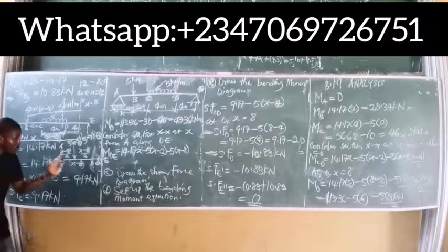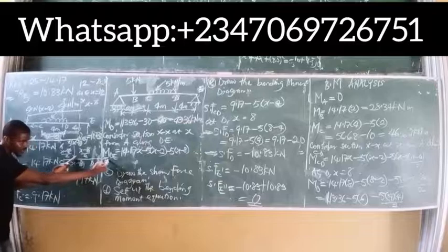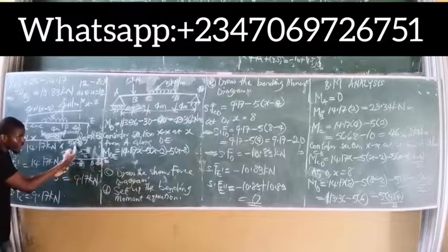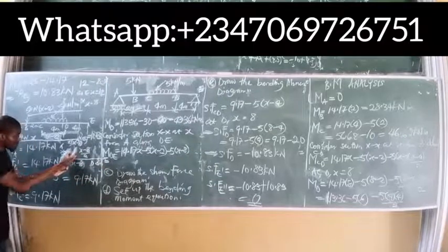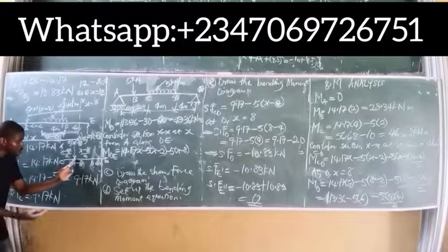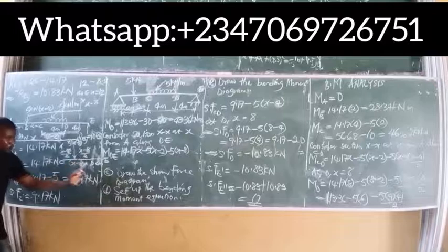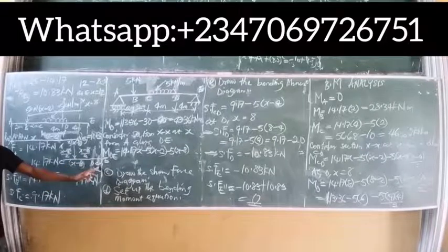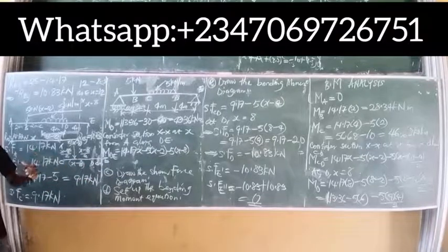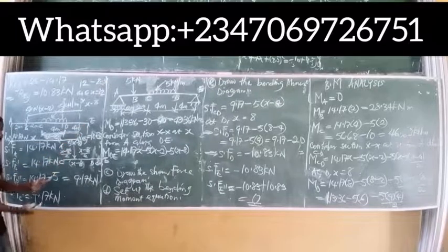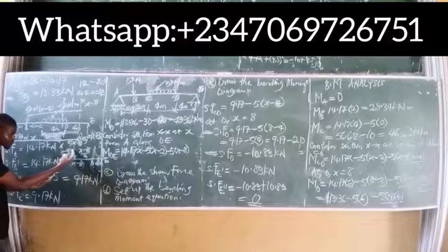So what is the moment of this force about point E? It becomes 5 into x minus 8, right? Times the total distance it takes this force to get to point E, which is simply what? x minus 8 over 2 plus 4. Because the aim is to eventually take moment at point E. If I've converted this force to a point load, it will act at the middle. Middle of length x minus 8 is x minus 8 over 2.